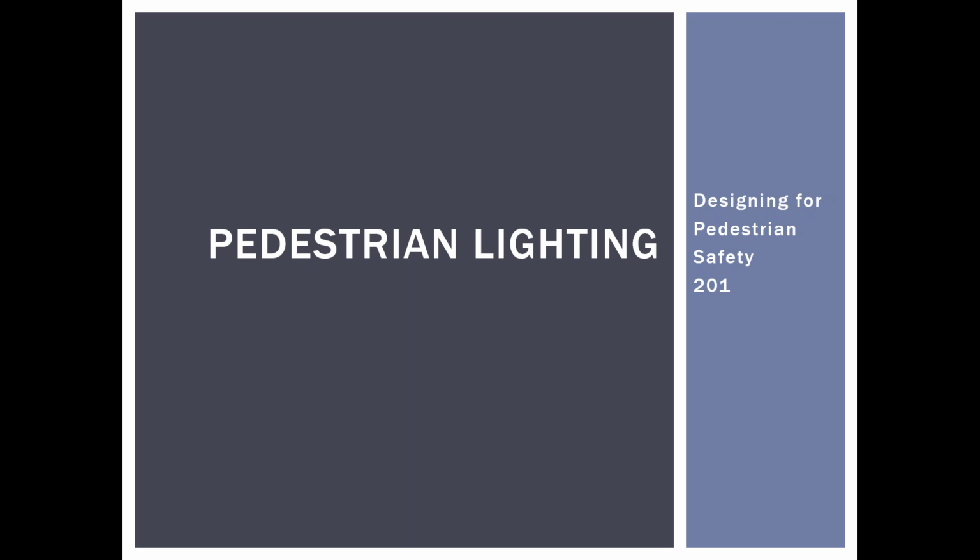The one thing about street lighting, it's not covered in the Manual on Uniform Traffic Control Devices, except there is some mention of street lighting in Part 6 of temporary traffic control. Street lighting is not required unless an individual agency has a policy to provide lighting. Some agencies do not have policies or requirements to provide street lights, especially in the rural areas.